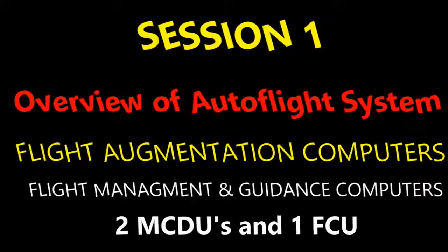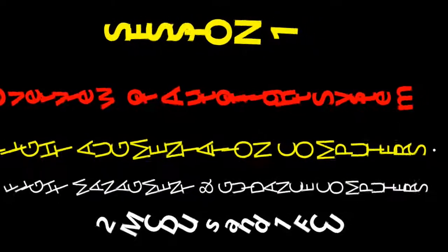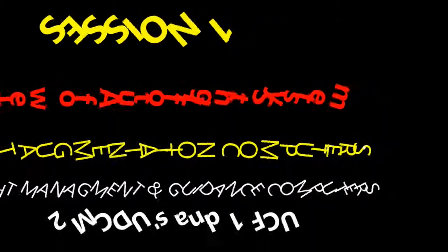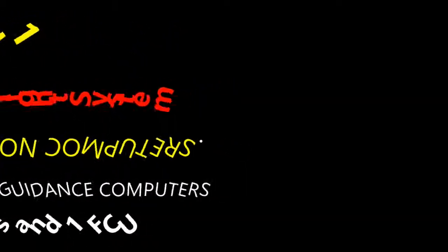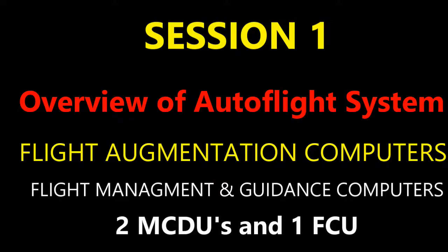Okay, so you also have a flight mode annunciator. That's part of the PFD, which is the primary flight display, like I just mentioned. It's just short, PFD. The flight mode annunciator is the top part of that. Okay, and what is that for? It's going to be showing autopilot and auto throttle engagement status, things like that. The other thing that's a characteristic of the annunciator is also showing the characteristic speeds on the speed scale. There's a speed scale as well, but the types of information you're going to find on here, again, like I said, related to auto throttle, your autopilot, flight director mode and status, and flight management messages will be on there.